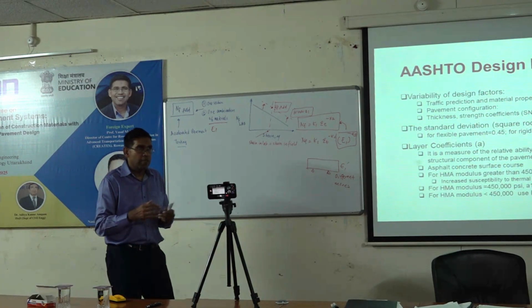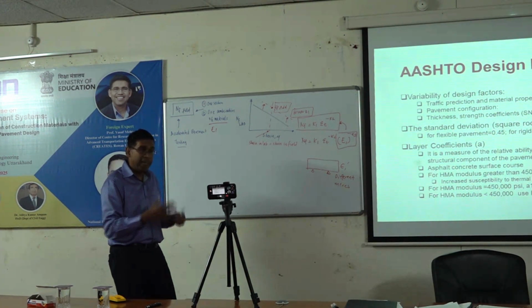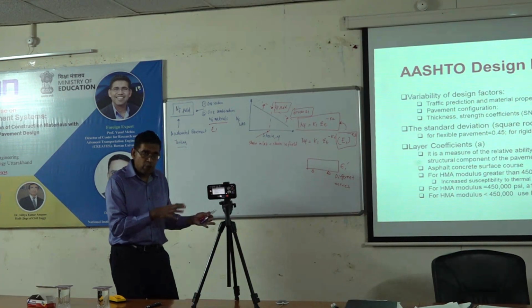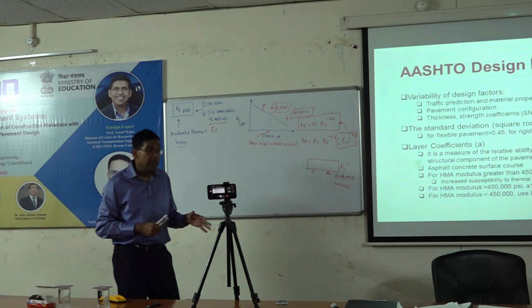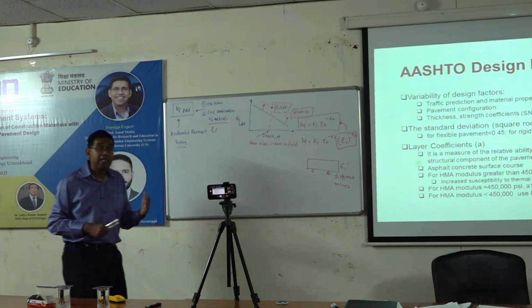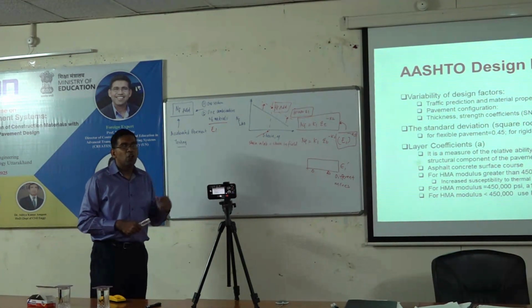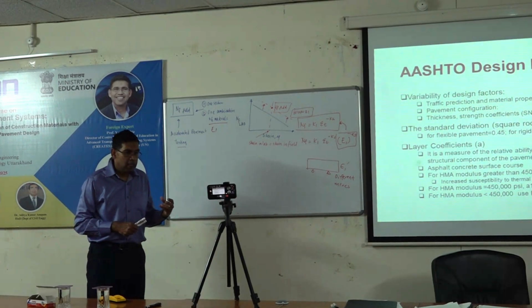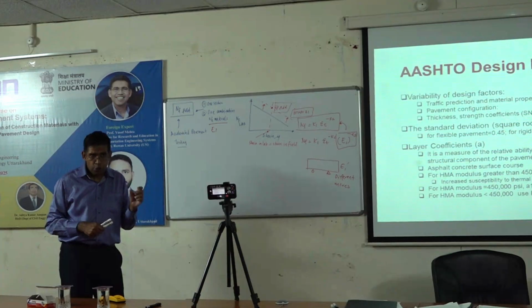There is enough factor of safety embedded in these designs to account for a broad range of mixes. So when we go into pavement ME, you will see that some of these mixtures will need a recalibration, but in the long run, the difference is going to be so minimal that it should be absorbed.